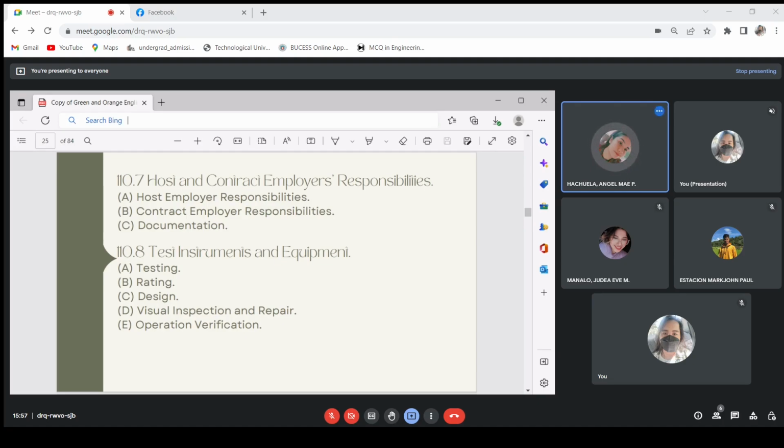If there is any defect or evidence of damage that might expose an employee to injury, the defective or damaged item shall be removed from service. No employee shall use it until a person qualified to perform the repairs and tests necessary to render the equipment safe has done so.